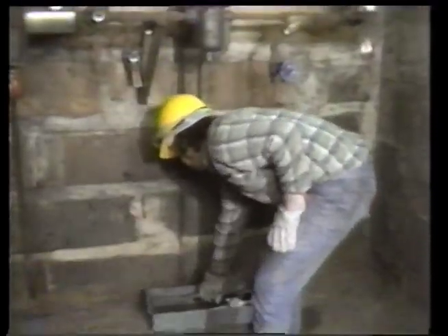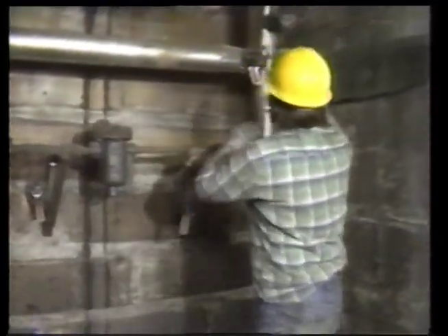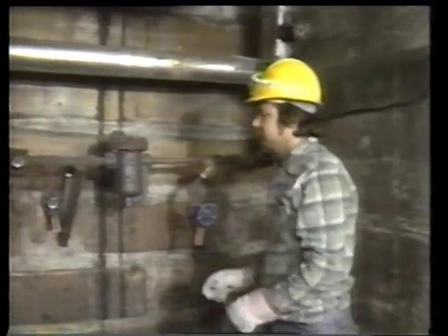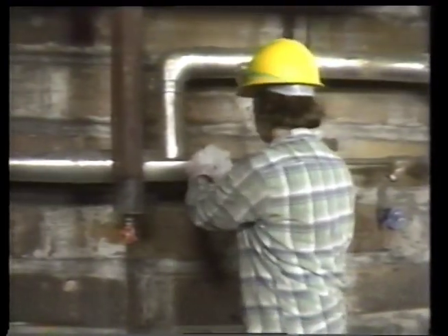Typically, traps should last an average of 3 or more years. Now, any trap that fails repeatedly within a 3-year period should be investigated and the cause of the failure determined. There are 2 steps to performing a trap survey: checking the trap system and checking the trap itself. In the trap system, any failure of the pipes, valves, or strainers associated with the trap could make an operating trap appear to have failed.